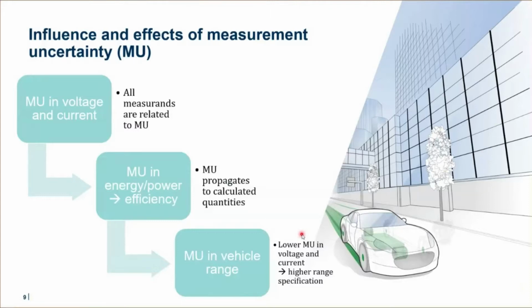In addition, all measurement equipment, independent from the manufacturer, each sensor, each power meter, contains a lot of different components, and all have manufacturing tolerances. Independent from the level of quality, it is impossible to build a really absolutely perfect system. For those two reasons, each measured quantity contains measurement uncertainty.